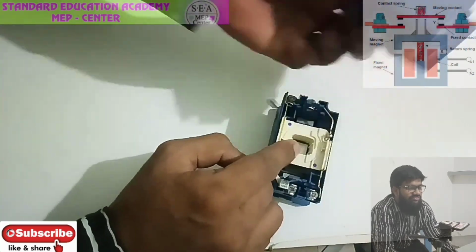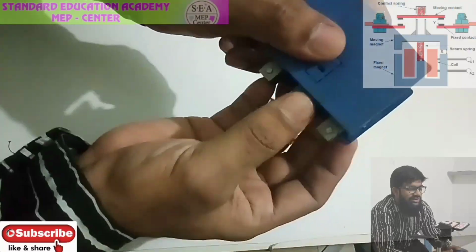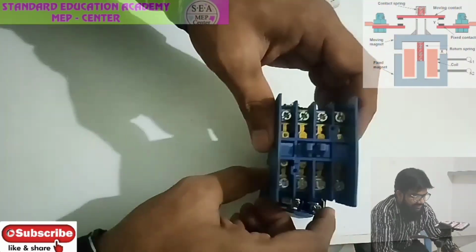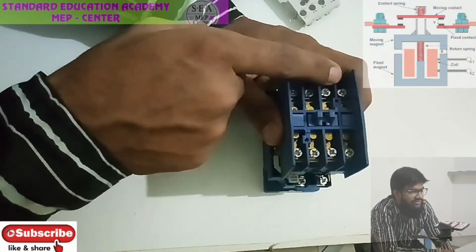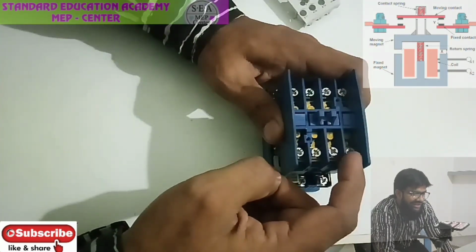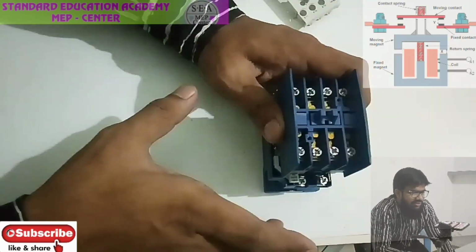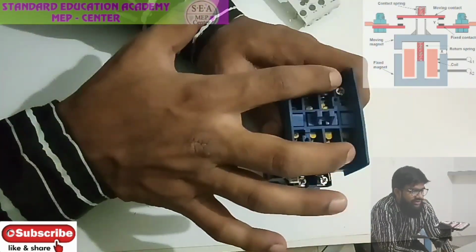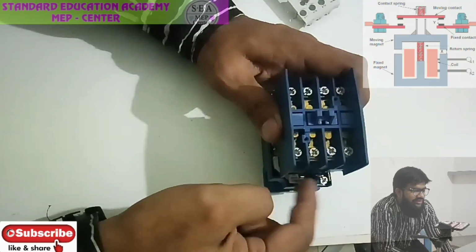Due to energizing of this coil, the spring which is there within this will tend this particular movable part towards the fixed part. As it is coming near the fixed part, automatically L1, L2, L3 with NO will come in contact with T1, T2, T3 with NO. That is 1,3 will be in contact with 1,4. There will be no contact between them till the coil is energized. So L1, L2, L3, T1, T2, T3 and auxiliary contacts will be in contact with each other when we are energizing the coil.